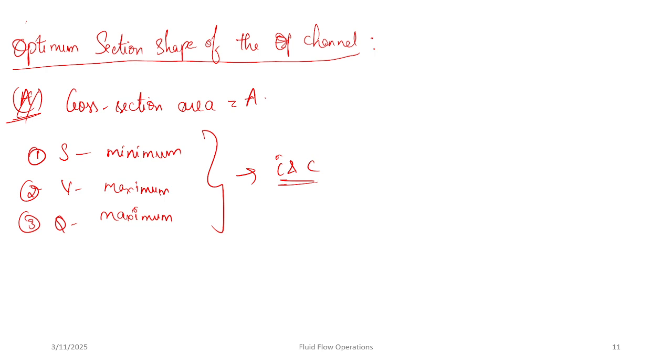Okay. Out of all the geometries, if you're fully charging this channel, that means if flow is complete in this channel, a circle has the shortest length of wetted perimeter, or it has the shortest value for wetted perimeter for a given value of A. Okay, so these calculations are already done, even for a sphere. You know that why do you use spheres for storing gas or LPG?